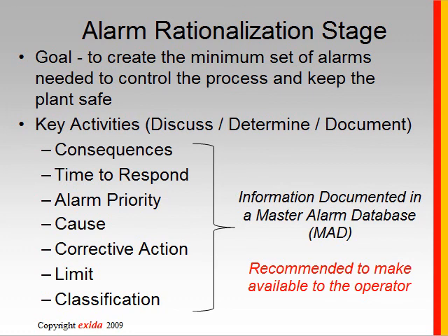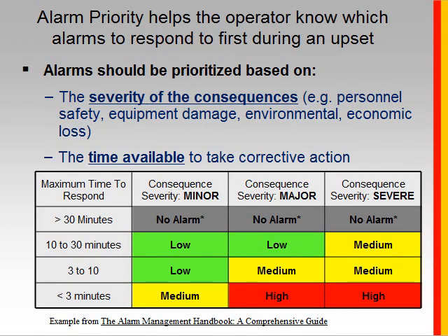And as you might imagine, if you're going through and you're talking about what caused an alarm, how much time you have to respond, what you should do to respond, that information is probably very valuable to the operator. So one of the other recommendations is to make that information available in some way, shape, or form to the operator. Best is online through the operator interface, and we'll talk about that more later.